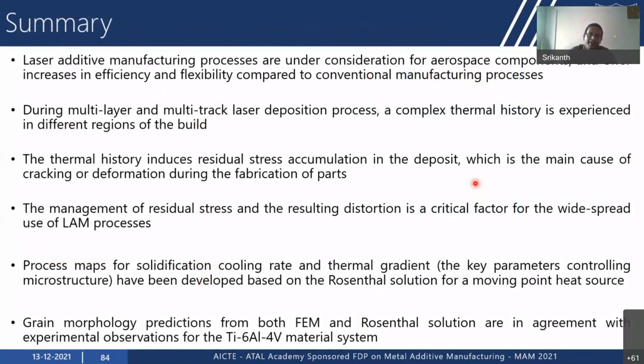So to summarize the talk, these laser additive manufacturing processes such as laser powder bed fusion and direct energy deposition are under consideration for several applications, in particular for aerospace applications, because of the increases in efficiency and flexibility when compared to conventional manufacturing processes in terms of the buy-to-fly ratio and the lead time for production of components.